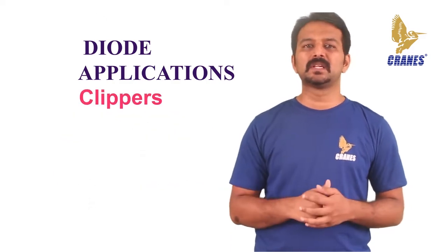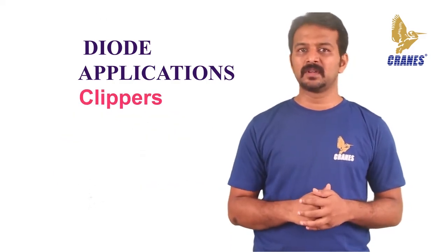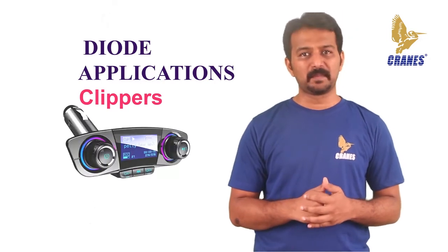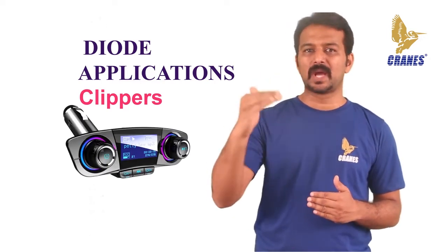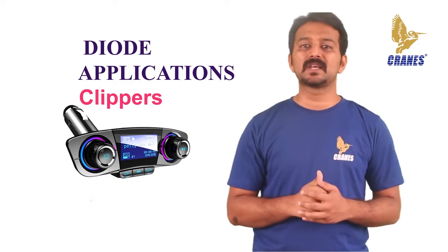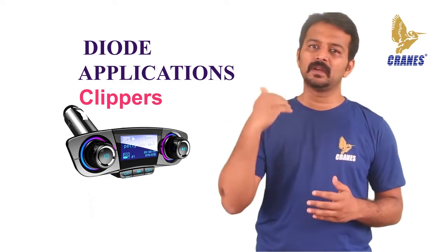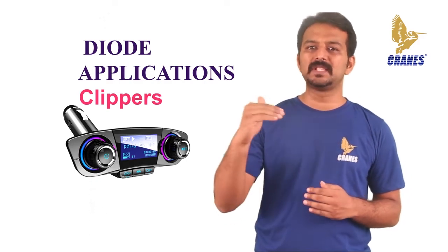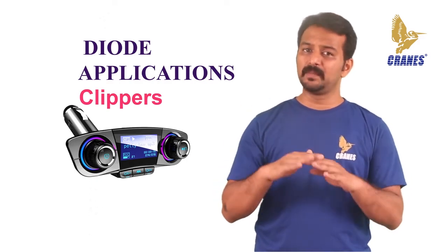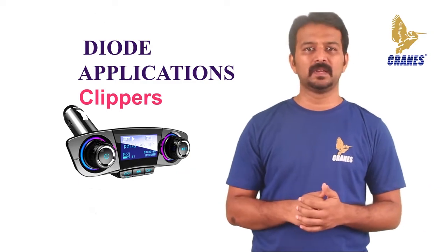So the next application is diodes in clipping circuits. Clipping circuits are used in FM transmitters where noise peaks are limited to a particular value so that excessive peaks are removed from them. The clipper circuit is used to cut off the voltage beyond the preset value without disturbing the remaining part of the input waveform.